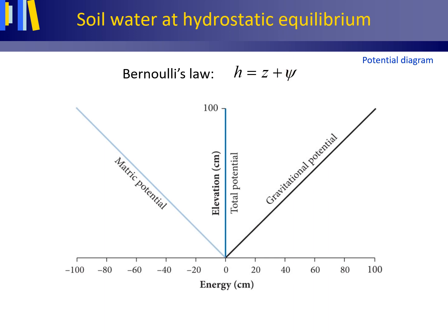For most practical purposes, it suffices to consider the total potential H as made up of a gravitational potential Z and a matrix potential psi when dealing with unsaturated water flow through the soil matrix. However, in specific instances, other potentials may also be important, such as the pneumatic potential when air is entrapped in the soil, or the envelope potential caused by overburden pressure from overlying soil.